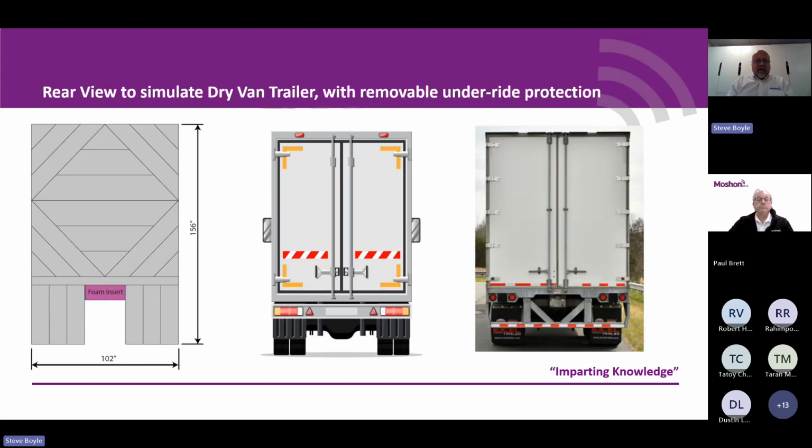So obviously we started off trying to make it roughly the same size as the dry van trailer. So the rear end, the rear axle. We also found that the space between the axles was important to help with the signature as well. The radar signature often bounces through, hits the bed and gets different detections along the length. It gives it a 3D element of a real truck rather than a flat slab at the front. So the gap between the wheels, the axles, and all that sort of thing were inherent in its requirements for a radar signature.